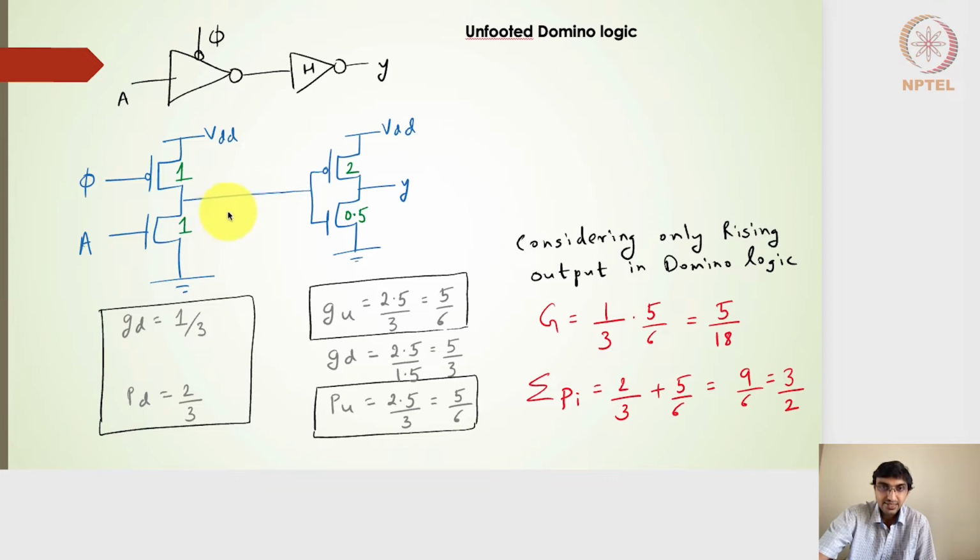So in that sense, if we are interested in the falling down signal here, why not make this a rising up signal really fast? And that's where the high skew inverter will be used. A standard high skew inverter is, instead of 2:1, we retain the size of 2 on the PMOS side. And on the NMOS side, we make the strength of the NMOS less. Normally we will associate with making the strength to be half that of the 2:1 inverter. And that's why we have the strength of 2 and 0.5.